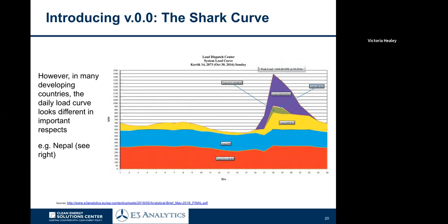This is Nepal's power mix in October 2016, showing the NEA, the Nepal Electricity Authority, basically their own national electric utility generation. Then there's IPP generation, which is mostly hydro, mostly run-of-river hydro, and then imports in yellow. The imports come predominantly from India. As you can see here, much of the Nepalese mix is hydro, and it just goes along, and imports are what are covering essentially the rise and fall of electricity demand over the course of the day.